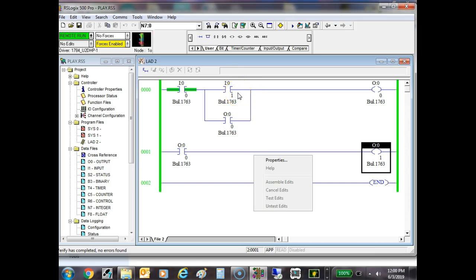So this is a standard circuit you run into. Anytime you run into a control and it's got a start-stop button on it, this is the way this works. So this would be the stop button. This would be the start button. What I'm going to do with this button is just momentarily switch it. And notice it went true for a heartbeat, then it went false. But what I did is I created a secondary path now where we can seal this thing in.